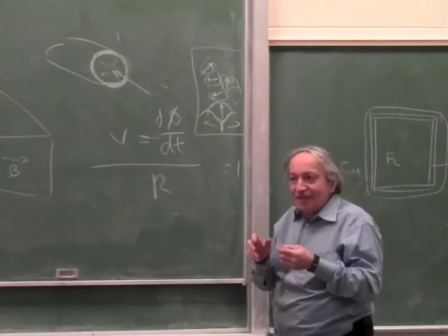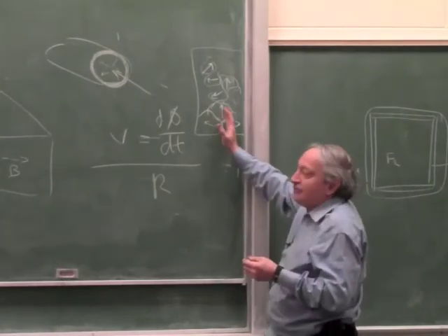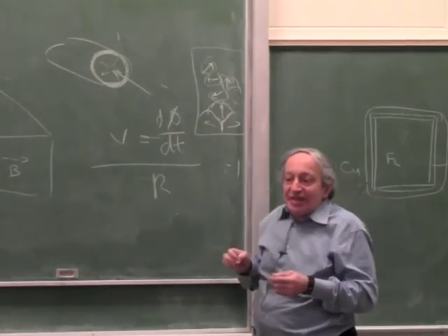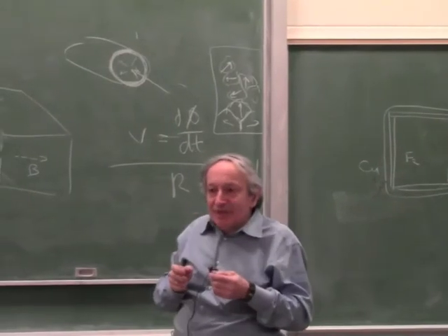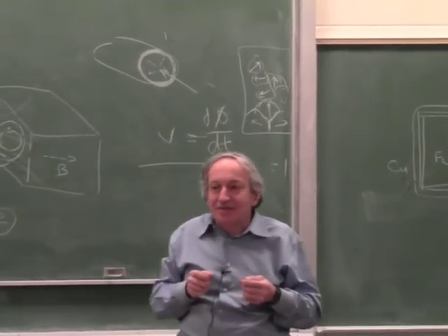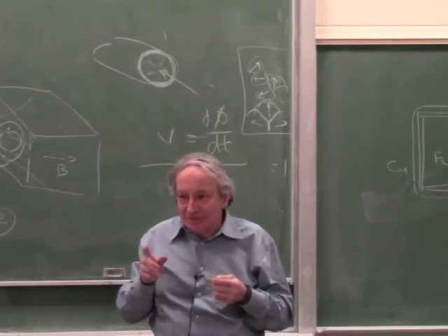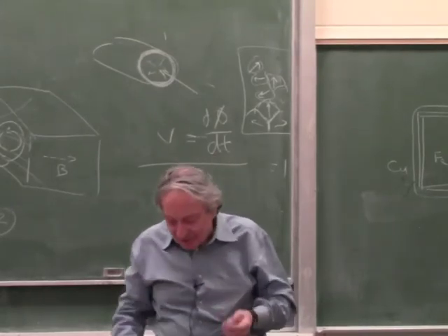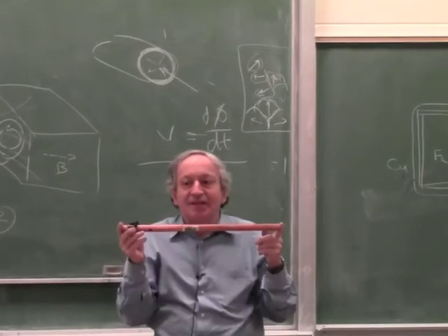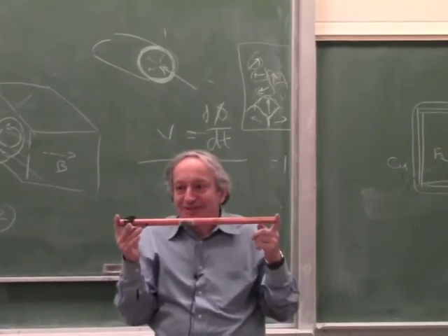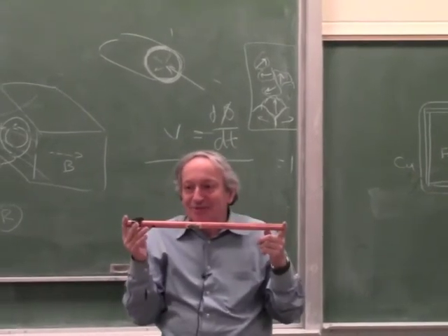Now as you magnetize it, these boundaries start shifting. So there is some mechanical movement as well. This is easy to prove by the fact that there is such a thing called magnetostriction. Do you know what magnetostriction is? If this is a piece of steel and I magnetize it, the length changes. So it means something mechanically has to move inside too.